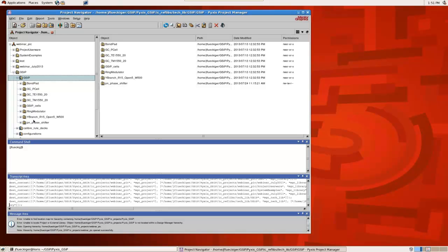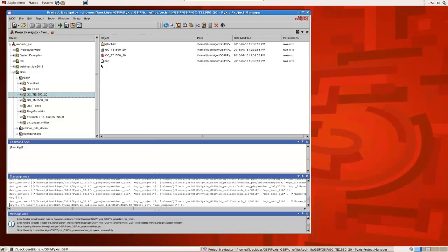Now it also has a cell library with photonic elements. For example, you have the grating coupler, the ring modulator, phase shifter, and Y branches. So these are modules that are included with the software, with the library. And obviously, if you are developing new elements, this library will grow to incorporate them, and this is part of PDK development. But let's start by creating an actual cell.